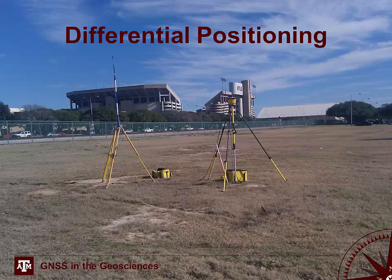Now you should have a better understanding of how differential GPS works, what the principles are behind it, what the assumptions of it are, as well as what the different types of SBAS and GBAS are. So you need to know what WAAS is, you need to know what CORS is, you need to know what the different levels of accuracy are with the different types of augmentation system covered near the end. And you should have a better understanding of how DGPS can be used to effectively survey a given area, but also what some of its disadvantages are and what some of the costs associated with it are. So remember, the application or the purpose of the survey is going to dictate what level of accuracy you need or want, which is going to dictate what equipment you need, and that's going to dictate your cost.